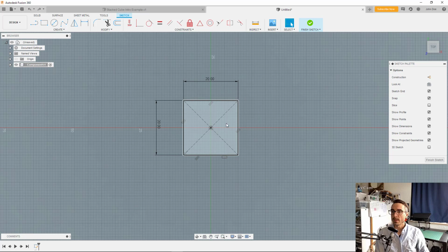The parametric design here, the fact that we've got some constraints, explains these extra little features that are hovering in various places. These double lines, for example, indicate that there's a parallel relationship. If I hover over the line or the symbol here, it'll kind of give a dull highlight to the line down below, letting me know that that's what it considers it to be constrained to. Those are parallel.